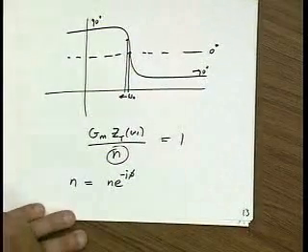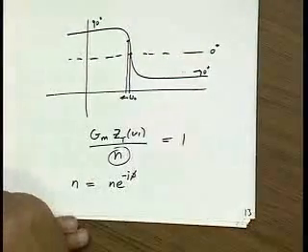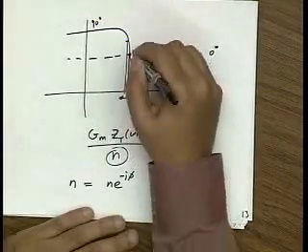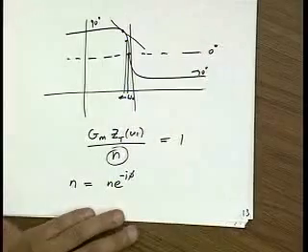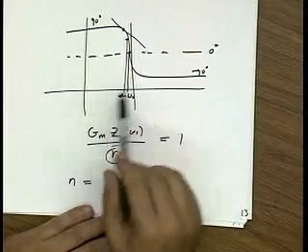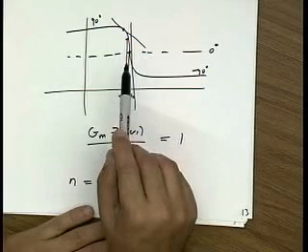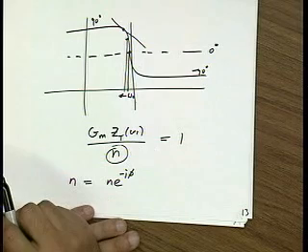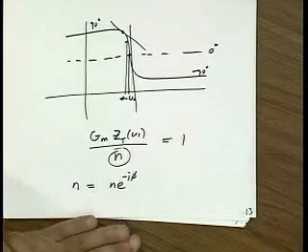So you might say, big deal. I'm not going to resonate exactly at omega naught. I can take that into account. Yeah, but I find out that the best point to oscillate is right here where the slope is maximum. You don't want to get to a point where this slope gets small, because the sensitivity of this circuit to phase noise is very much related to the slope. The higher the slope is, the less sensitive it is to noise on the phase. And so if you want the circuit to have good phase noise performance, you want to oscillate at omega naught.